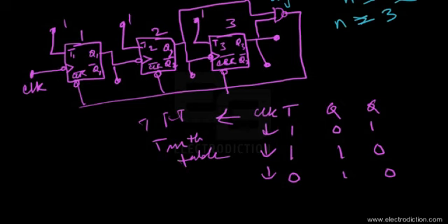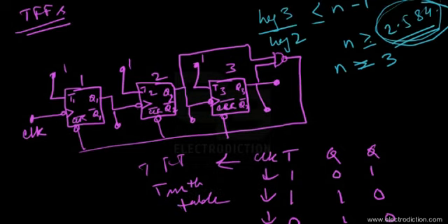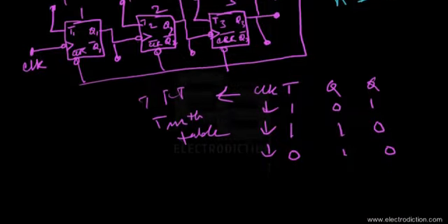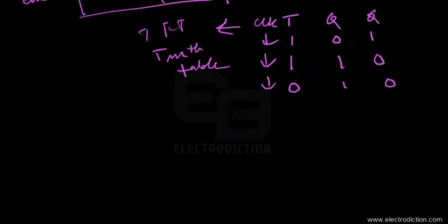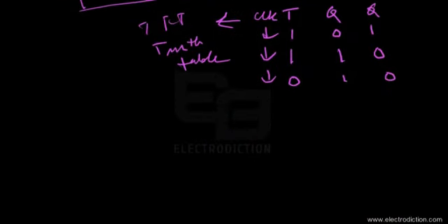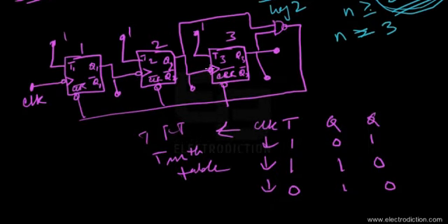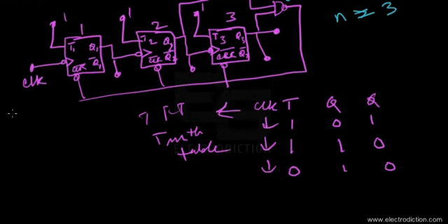Keeping that in mind, and with a little recapitulation about T flip-flops, we'll go into how this counter functions. Let me take the red color, and I'll write down the states over here. Here are the states, Q3, Q2 and Q1, and this is R. R is the output from this NAND gate, as you can see over here.